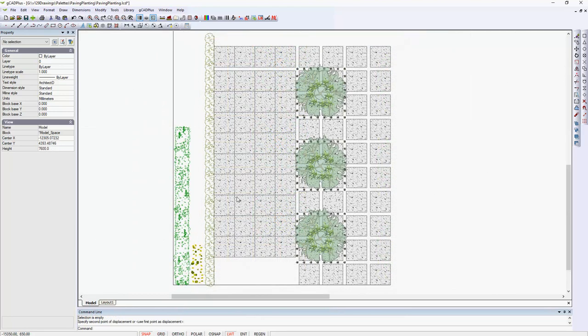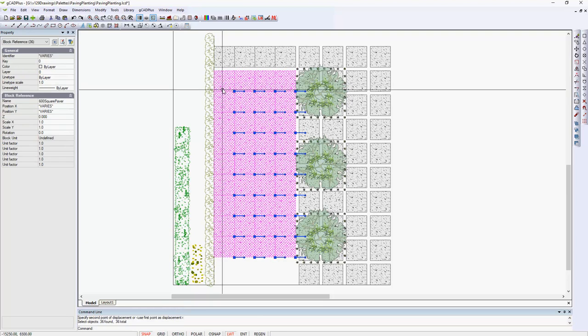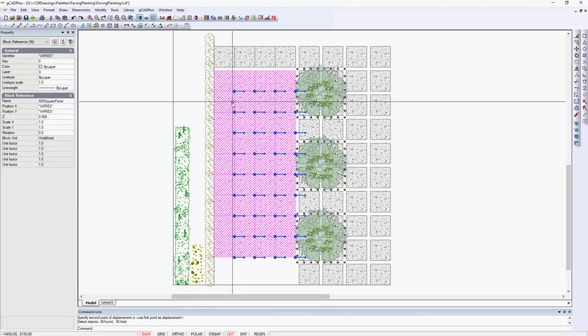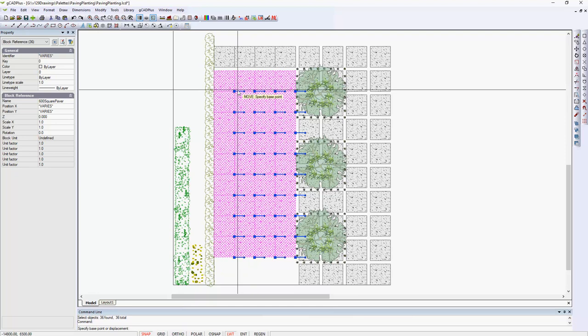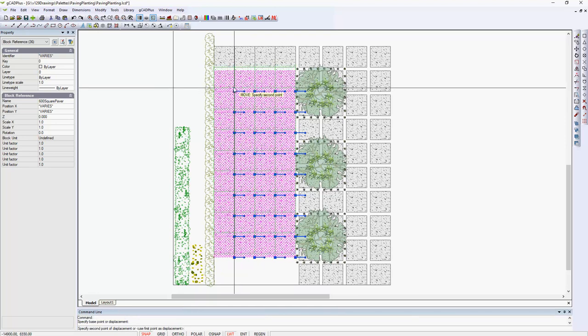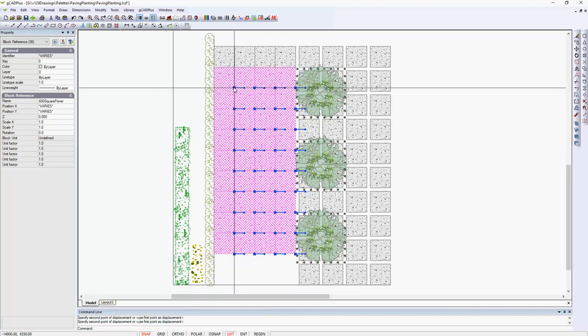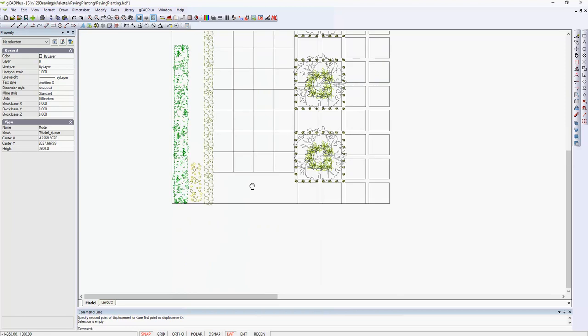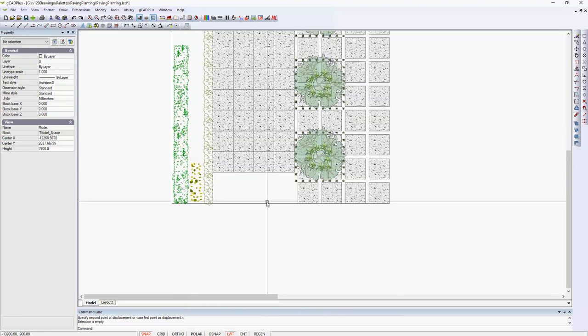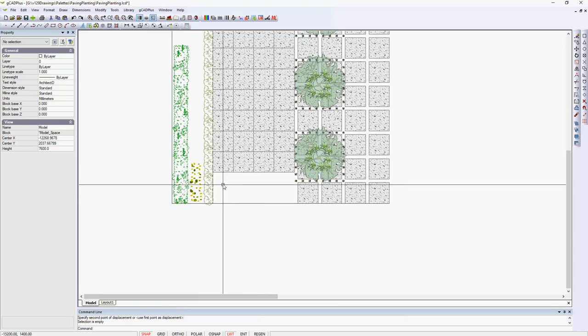Well, I'm continuing the design work now, still on a 100mm grid, and I can grab hold of all of these. I've decided to put paving butting one another in this area, and I can select those and move them up and see how neatly I can butt those. 600mm paving stones are now joined together with a butt finish and providing me with a nice walk-through space.